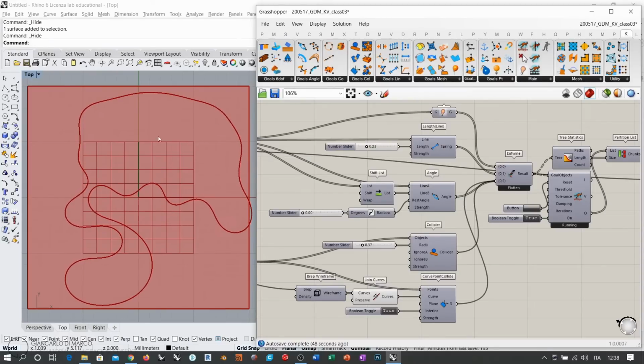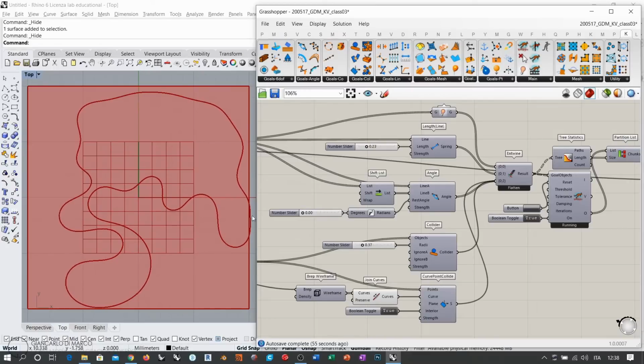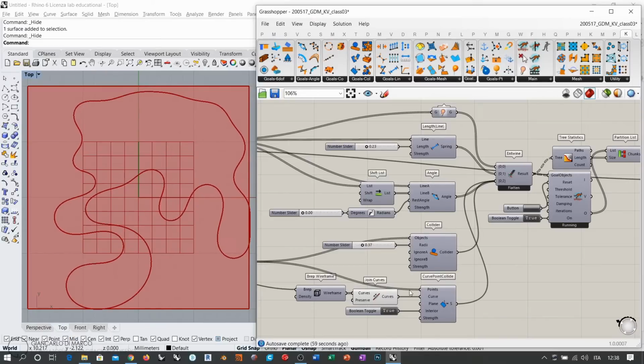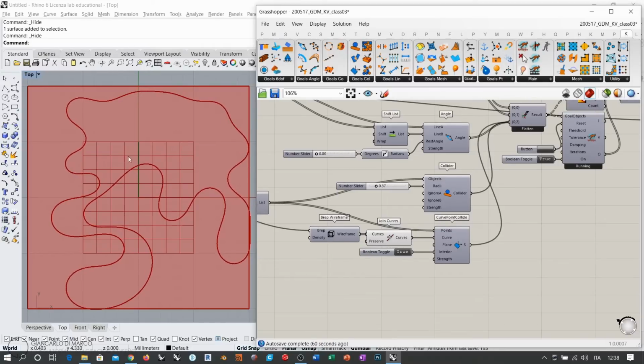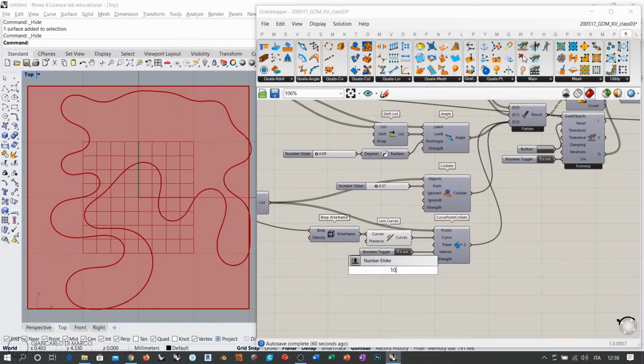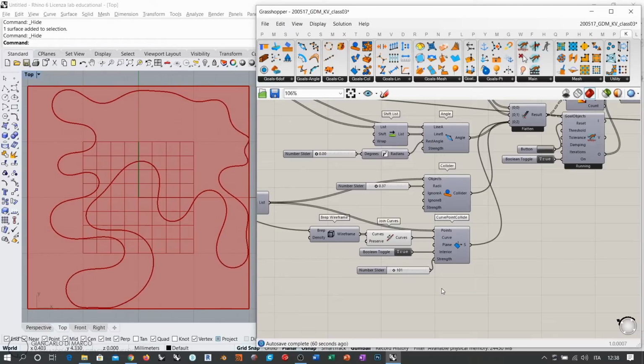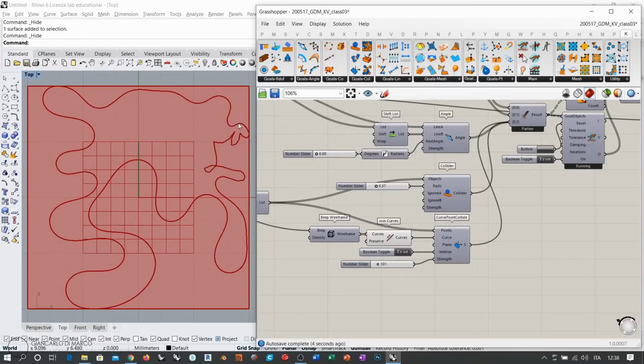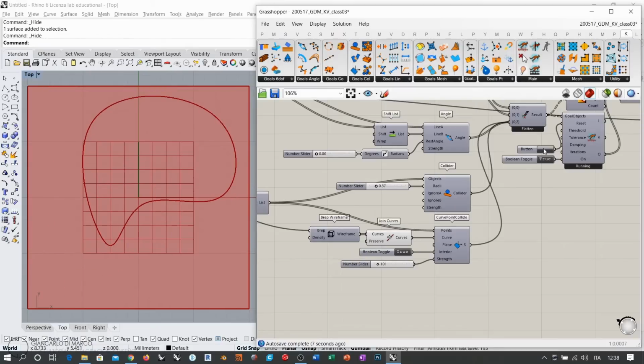So you see that these things start to adjust smoothly. Eventually it goes over the boundary because of the strength of this goal. We are going to adjust strengths in a while. Actually, we can also start doing this in order for this curve to remain on the inside. So I will take a 0 to 1 slider and set it as strength for our boundary. You see that it instantaneously pushed the curve away, and this became unstable. This is also something that you might want to do at the beginning, to avoid instant deformation.